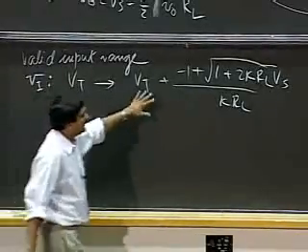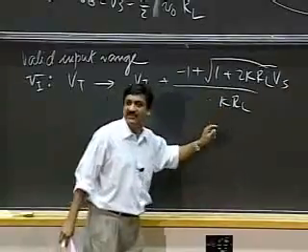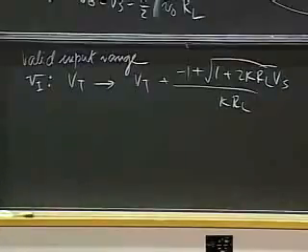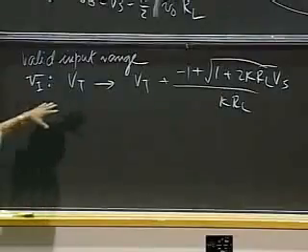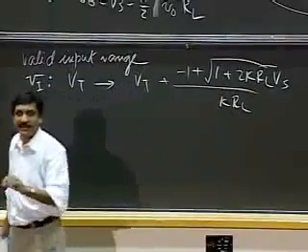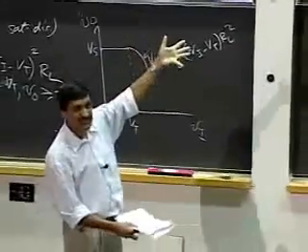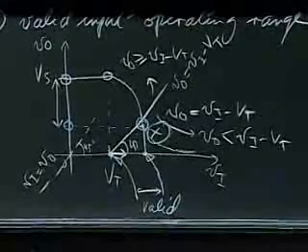And again, remember, I won't dwell on this equation because you will get a different set of limits for other devices, for other circuits containing a MOSFET, or for other outputs that one may be focusing on. What's more important here is not so much the results, but the process I've gone through, how did I get here? I looked at the graph and said, look, the MOSFET is in saturation in that regime, and I'm finding the bounding points of the regime of saturation operation.